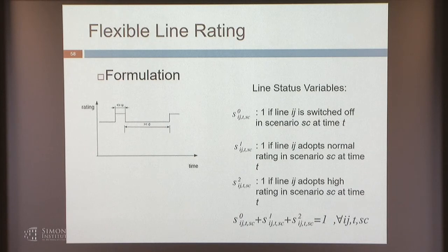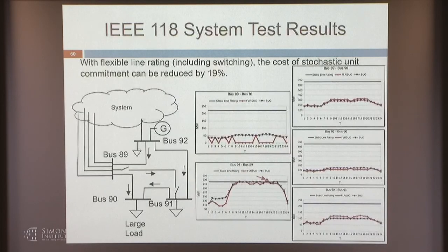And what you achieve by doing that is a hedging mechanism against the uncertainty of the wind. So by doing that, you can be more aggressive or dispatch cheaper day-ahead generators. Most of the benefit accrues in the day-ahead dispatch, because you know that you have a recourse action that you can rely on in the second stage. So this is kind of to illustrate how things happen.